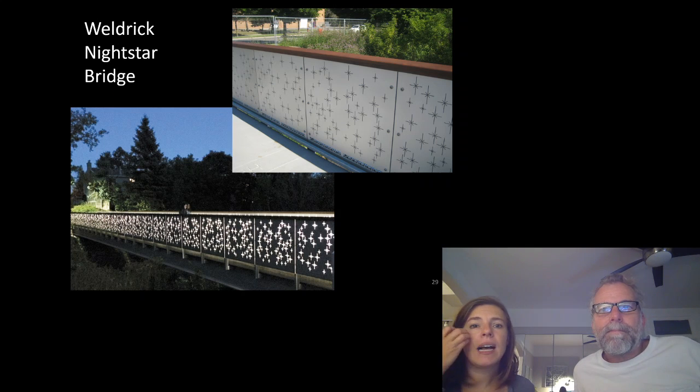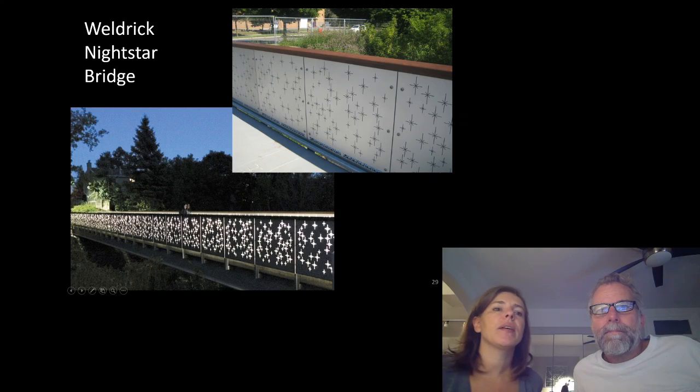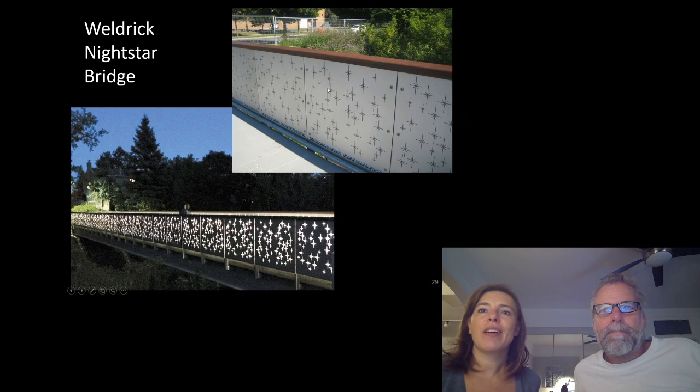This is an interesting kind of aesthetic bridge where they light up inside the railings. It doesn't look like the railing is actually structural. It's doing its guard work, but even these just look like infill panels. Hidden inside the two pieces of panels is a piece of upstand steel, and there's just a steel girder spanning across the gorge.